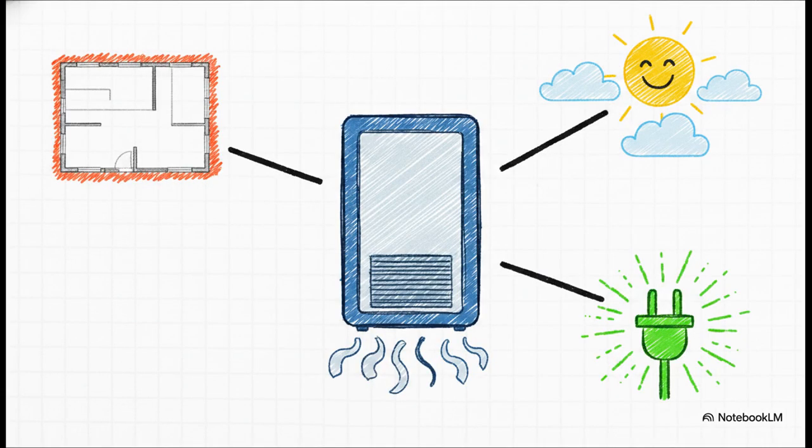So let's build a quick pro-level decision matrix to make this super simple, starting with exactly when you should choose a heat pump. A heat pump is absolutely your best choice if you are conditioning those fluctuating exterior zones or if you're in a mild or warm climate where winter efficiency drops aren't really a huge deal. It's also the ultimate go-to if you explicitly need both heating and cooling in one package, or if you're designing for decarbonization and want a completely all-electric setup.